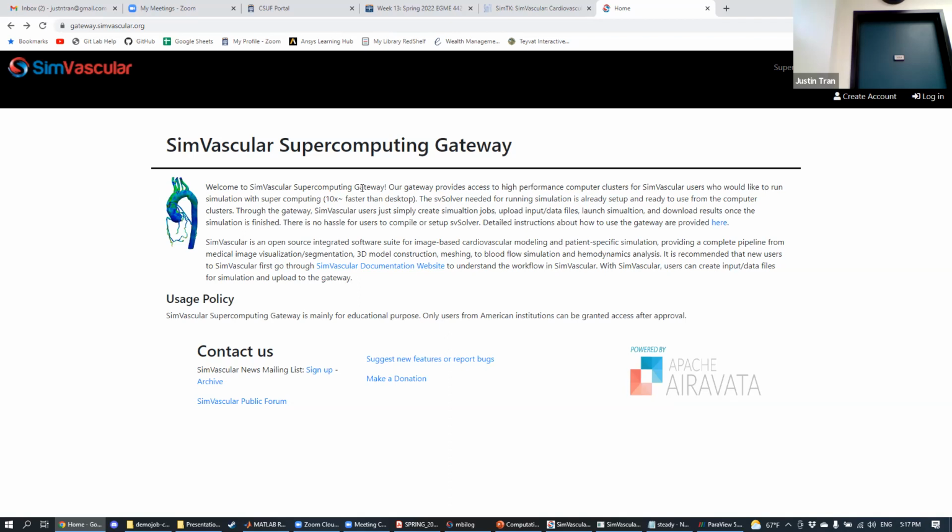The good thing is that it hasn't failed, and if it hasn't failed, that means it must still be working. I will say that SimVascular was designed by underpaid grad students. What can happen sometimes is the mesh fails, and then you can access your model until you close it out. Sometimes the best thing is to restart the software. And if you're having trouble, we can continue working on it.